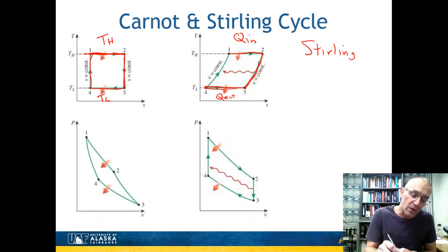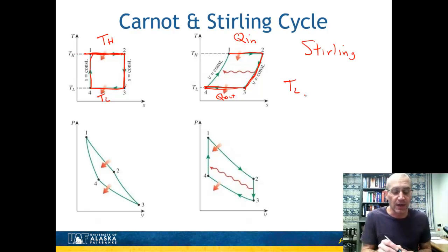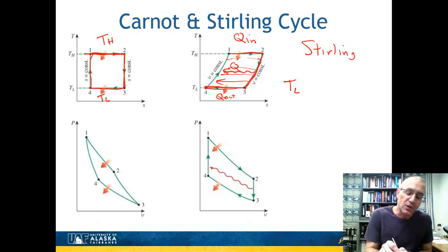And it's cooling down, and if it were losing heat, it couldn't lose it to some sink at TL, like in the Otto cycle or diesel cycle, where we'd have heat transfer across a finite temperature difference. So it uses this thing called a regenerator, where the energy stays within the system, and it gets dumped over to a fluid that's on the opposite side. We'll see how we do that in practice. That way, since there's always heat transfer across an infinitely small temperature gradient, that is also isentropic.